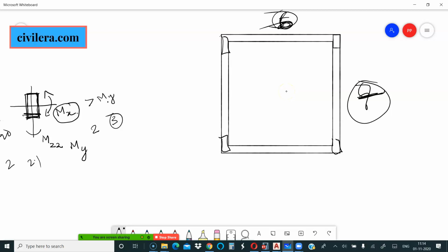Now, if you go by the deflection rule of slab, which I think you know, L by D ratios, this is a single span slab, so this is a discontinuous slab, so that comes to around 20. So the depth of your slab is going to be very huge, maybe more than 175 to 200 mm or even more.